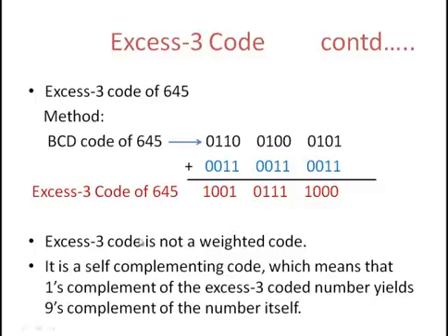Further, some features of excess-3 code are given here. That is, excess-3 code is not a weighted code. It is a self-complementing code, which means that the one's complement of the excess-3 coded number yields the 9's complement of the number itself. And this property of excess-3 code helps in performing subtraction operations in digital systems.